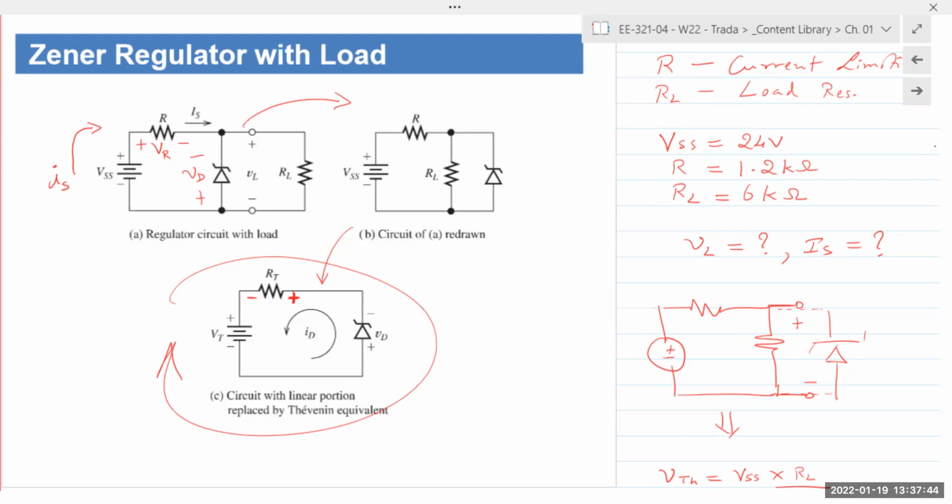So where is the excess current going? It's going to the Zener diode, right? So the Zener diode has a limit, and that limit is described by PZ max, the maximum power dissipation of that Zener diode. Okay, so remember the first slide of the Zener diode, there are two specs. The two most important ones are the Zener voltage VZ and then PZ max. And from VZ and from PZ max, we can calculate what the maximum current the Zener diode can handle. P is equal to IV.